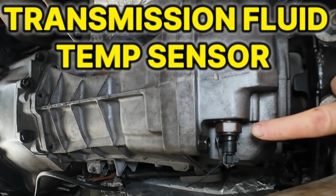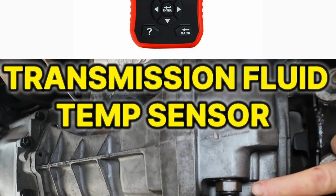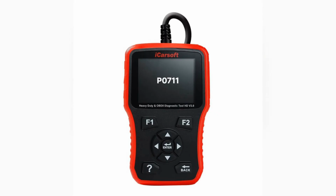How to eliminate or clear fault code P0711. Some suggested steps for troubleshooting and correcting fault code P0711. Change the ATF fluid and filter. Top up the transmission fluid to the required level. Flush to clean the transmission's internal pipes. Test, if necessary, by replacing the faulty transmission fluid temperature sensor. Troubleshoot mechanical faults inside the transmission. Check connectors and wiring. Check for an intermittent or faulty PCM.